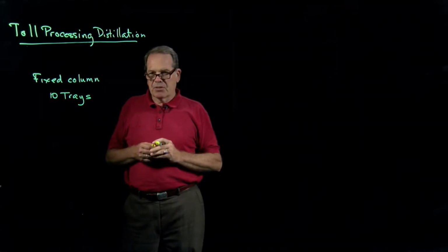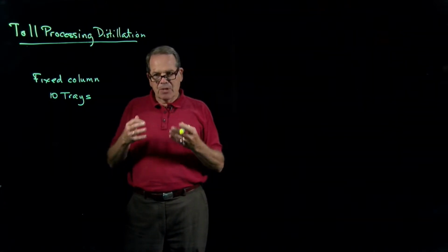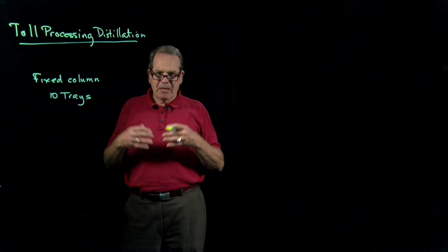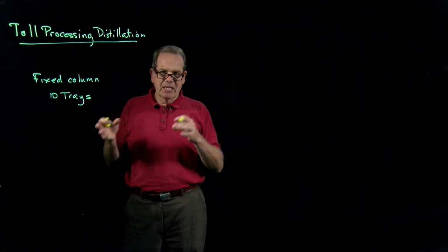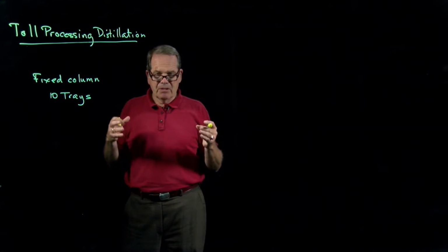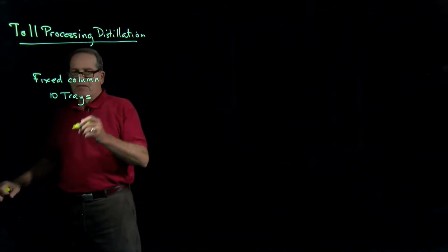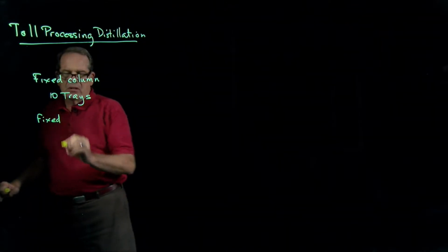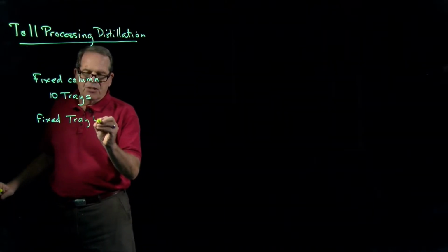The other thing that's sort of interesting is we need to decide on what the products are going to be. We're given a separation to make, but the client would like to recycle or be able to resell the solvent as a way of reducing its process costs. Obviously, recycling or reselling would be the best because they don't want to spend the money to treat this or to put it to a flare. That would be very expensive and costly to their process. And then the other thing that's unique here is that because we are distilling the same thing, we're going to have fixed tray efficiencies.